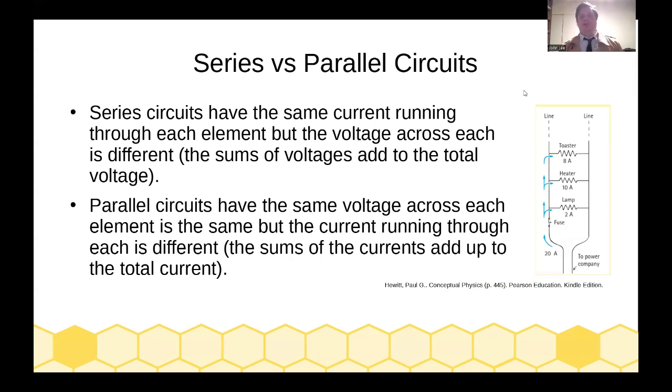In order to avoid this, we invented something called fuses, which are elements placed in series before the current starts passing through all of these objects. If the total current is greater than a certain amount, the fuse will burn out and switch off the power, because you're using too much current and it becomes a fire hazard.